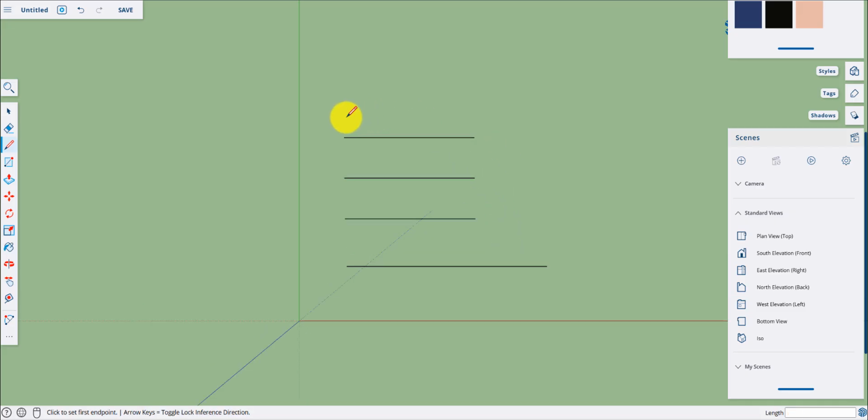Now try that doing it at 10 inches. Move to the right. I'm going to type in 10. I'm going to press shift, apostrophe, enter, and you'll see how much smaller it is. So that's how you make straight lines. Each tool, whether it's a rectangle tool or a circle tool, will be slightly different, and we're going to follow those up in a moment. So once you're able to make these lines at 10 feet and 10 inches, you can go back and grab your eraser tool and just get rid of them for right now.